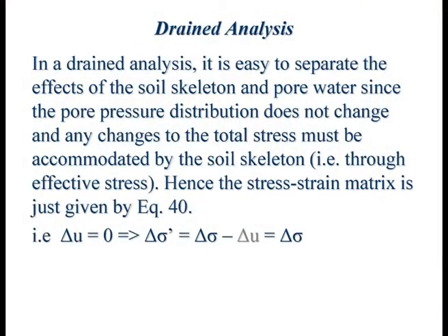So basically, programs that are smart enough will let you bring the boundary further out and actually move towards a seepage condition, near to the excavation. It's just something that you need to be careful about. Okay? So this is the trick about the drain condition. But internally, it's very straightforward because the pore pressure is calculated separately of the soil skeleton. Separately. It's not calculated together. So you don't have a problem.